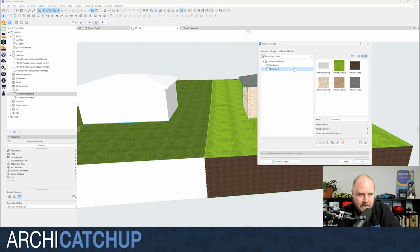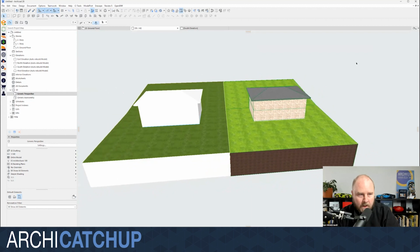So the methodology of creating an existing building using this SketchUp method, converting a physical asset, or a virtual asset, I mean, or an existing asset into something that you can bring between projects from projects past, while maintaining the way it looks, is to basically export this textures folder, and then you make sure that's part of your project library together with your new SketchUp item object that just turned into a GDL object. So that's one methodology that we adopted.